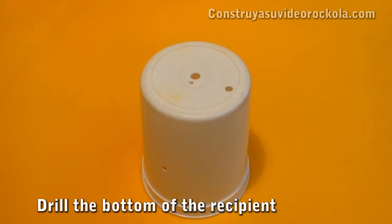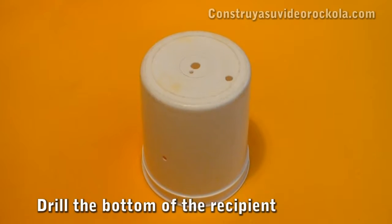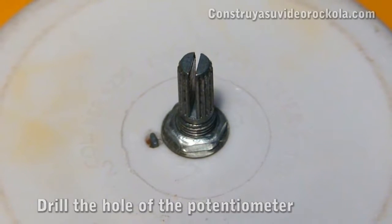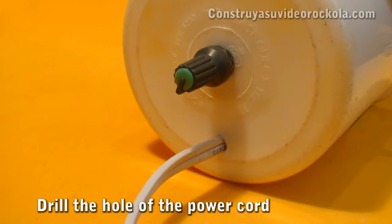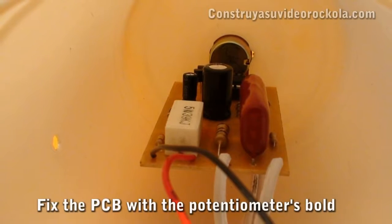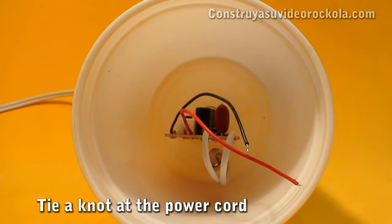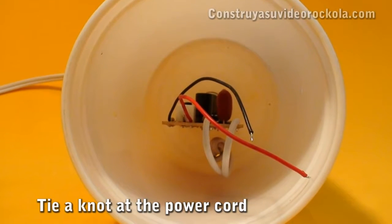Now comes the installation of the oscillator circuit in the ice cream bowl. Three holes must be made in the back, one for the potentiometer shaft, another to fit the pin-up, and at the bottom another hole where the power cord exits the circuit. The card is installed, securing the pot with a nut and washer. It is important, before pulling out the power cord, to tie a knot so that when we pull the cable we do not abuse the circuit.